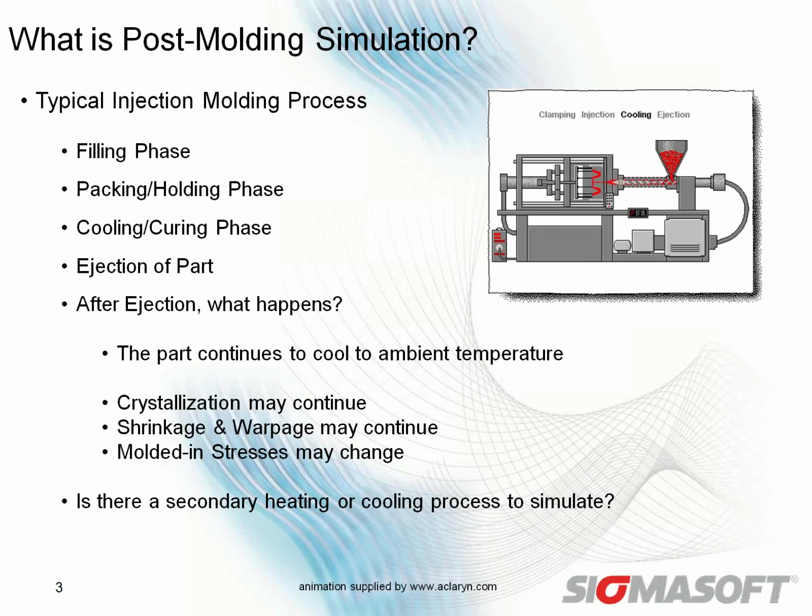Your typical injection molding process, of course, goes through some sort of filling phase, typically velocity-controlled injection of the polymer into the cavity through the runner system. Then you switch over into a packing and holding phase to compensate for shrinkage and allow additional polymer to be pushed into the cavity to offset the shrinkage that's occurring. Then we move into a cooling phase, typically after your gate freezes, ideally, and hold the mold closed for a certain period of time until that part is ejectable.